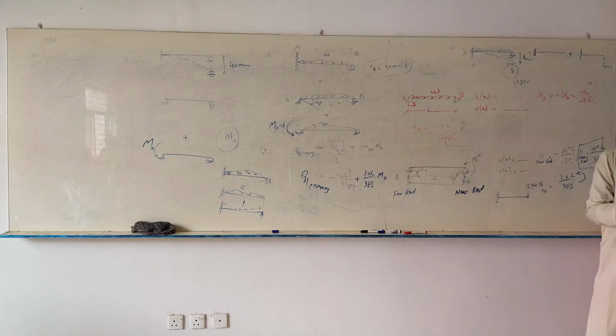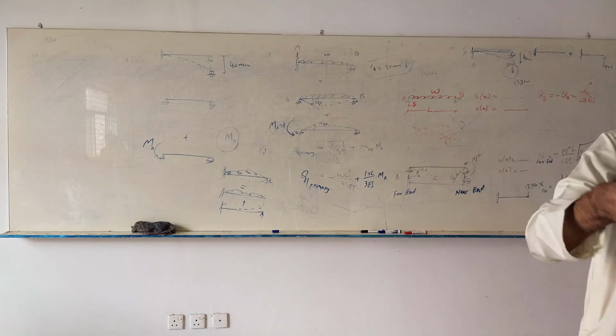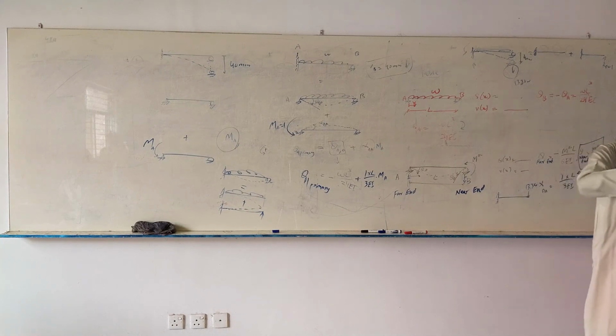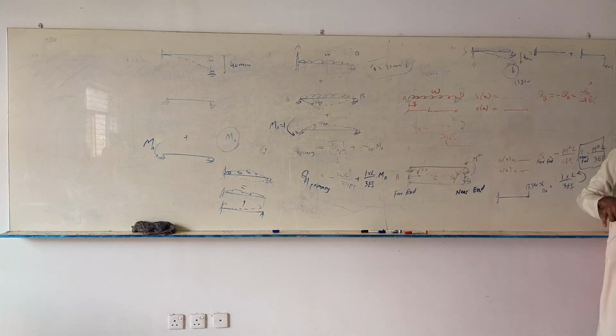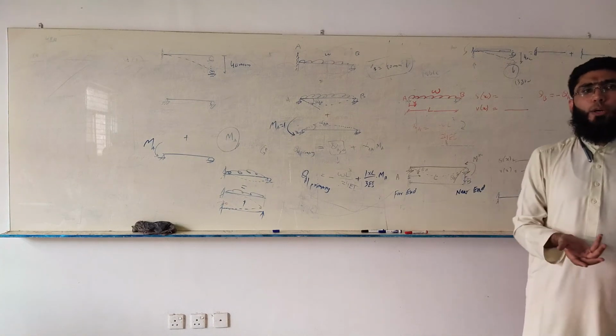You impose certain displacement on that indeterminate structure, you are going to induce certain reactions, certain bending moments, certain shear forces, everything that can be done by applied load. So one way is to apply loads, 30 kN per meter, 50 kN-m in moments. The other way is to impose displacements. Okay? So try to understand this point. Imposing displacement is one way of loading a structure.